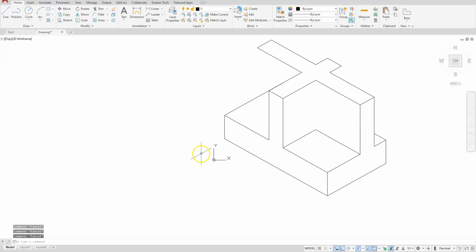Let's go ahead and escape out of this, and now let's put in some vertical lines. I'll use copy as well for this one, so I'll select this line, this top grip, spacebar one time, or until you read the word move, then select the word copy, then place it at that endpoint, this one on the back side, and it shows up here.